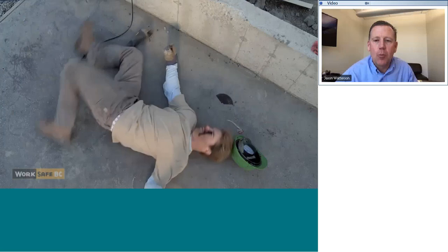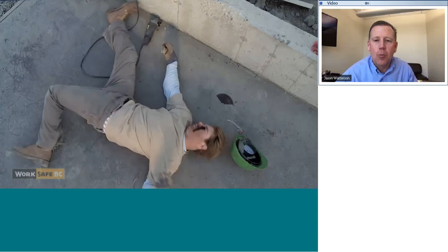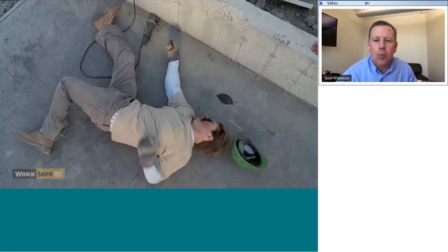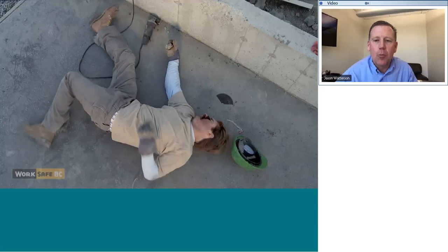Pressurized work, so if I'm doing pressure washing or hot taps, have those things available. Even sprinkler work. We've had some really unfortunate incidents where people working on high pressure sprinkler and hot taps in water lines and various places had a blowout, and in at least one situation I know of, a person lost their eye from this pressurized water that came out of a sprinkler line. So these are situations where that would be appropriate.